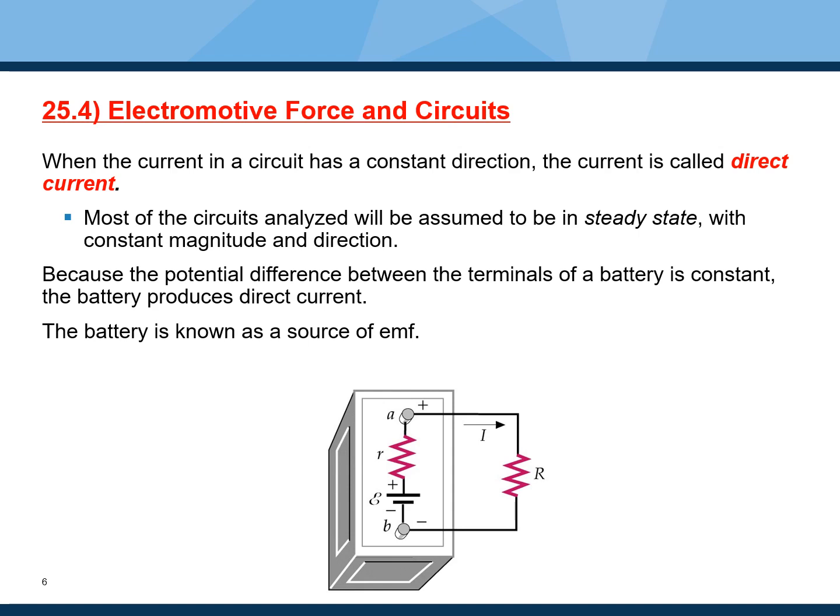And the reason the battery becomes warm is that as you draw a lot of current, a real battery is not just an idealized battery like the one shown out here, but rather a real battery is a combination of an idealized battery plus an internal resistance.